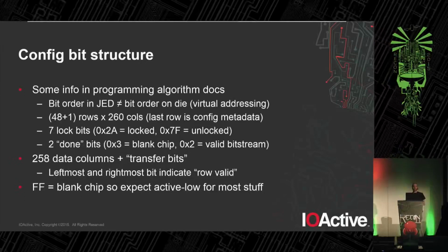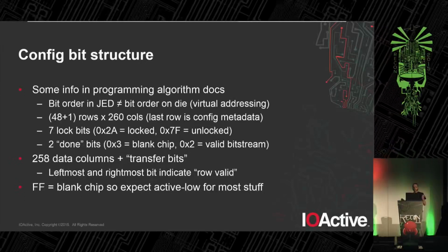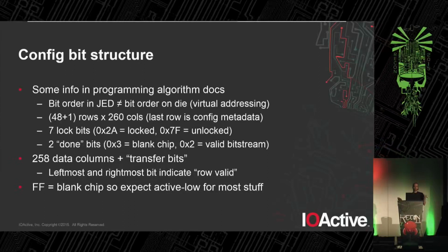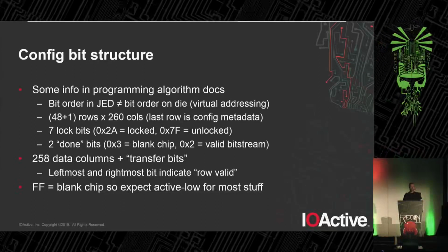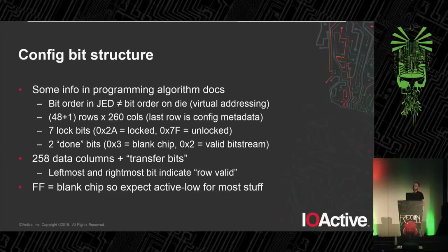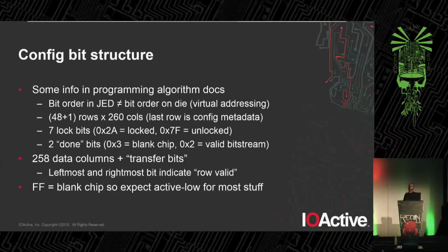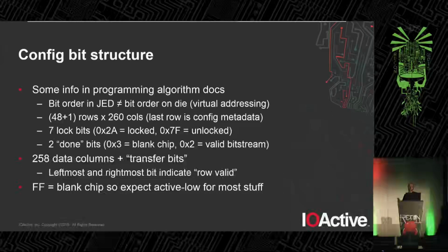The remainder are what we call transfer bits, which, as far as I can tell, you just put as a constant 0. It just indicates, hey, this row of EEPROM has actually been programmed. We didn't abort halfway through programming. There is some documentation of this in a patent from Xilinx, but it didn't really give enough detail for me to figure out why they are doing this.